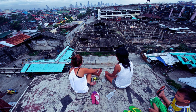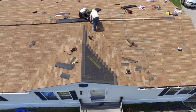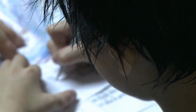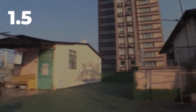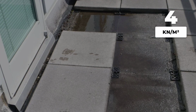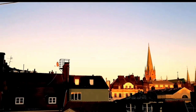Live load is the variable weight from people, movable objects, or temporary installations, maintenance crews, snow, or, in the case of rooftop housing, daily residential activity. Most building codes set this live load at 1.5 kilonewtons per square meter for residential roofs. Add these together, and the standard roof slab is designed for a combined load of roughly 4 kilonewtons per square meter. This is a ceiling that defines the safe boundary for what the structure can bear.